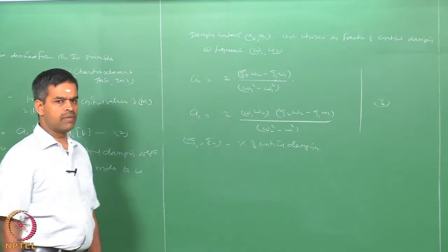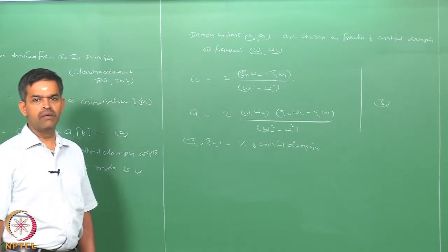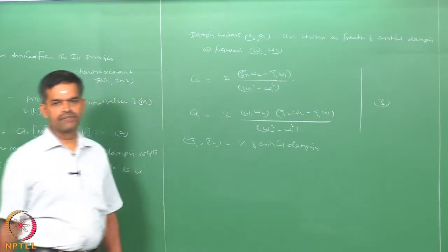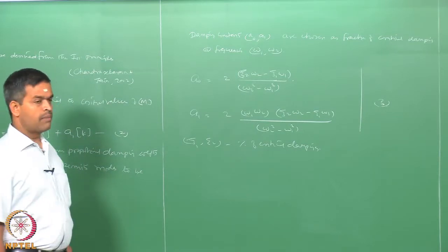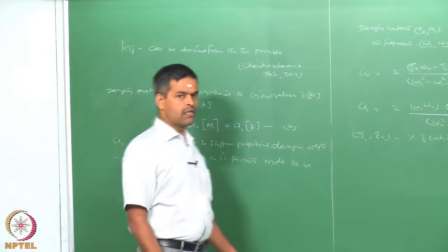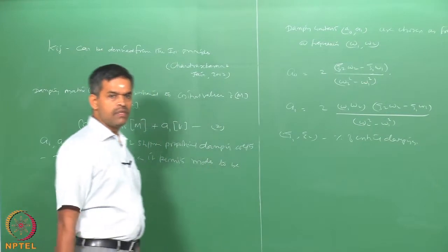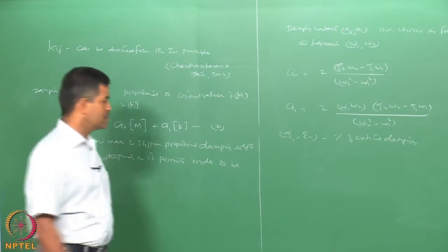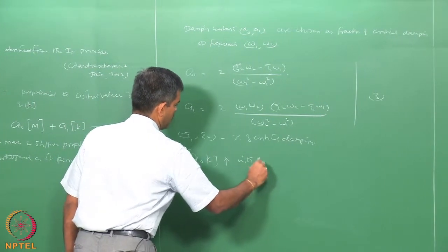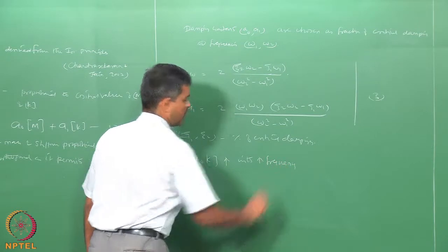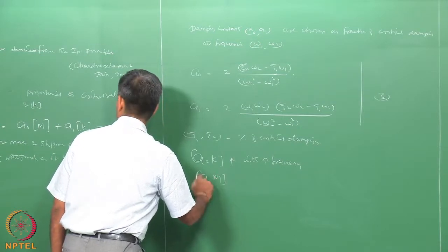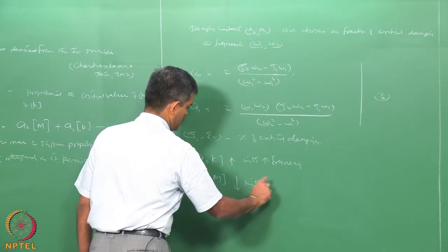Okay. The corresponding frequencies omega 1 and omega 2 are chosen in such a manner. So, the two different frequencies are chosen out of 6, so that a suitable mass and stiffness proportional damping can be used in the system. So, the damping attributed to A1 k increases with increasing frequency, whereas A0 m will decrease with increase in frequency.